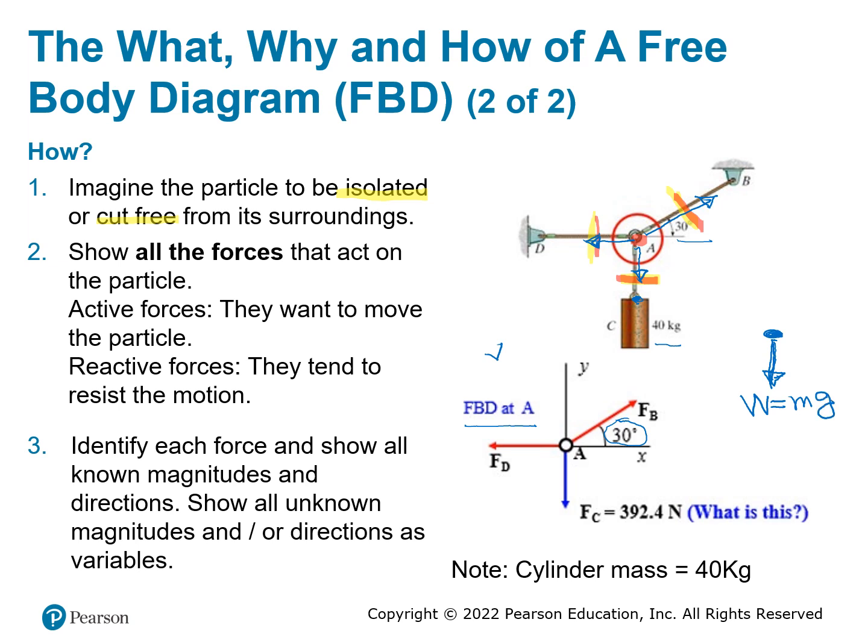When I look at this point, I'm going to cut off the top. Remember, when you cut off something, you always have to draw a force, which is a reaction force. This force is a cable, so it's going to be a tension force. Tension force will be away from the object. So this is the tension force. That is the tension force of A and C.